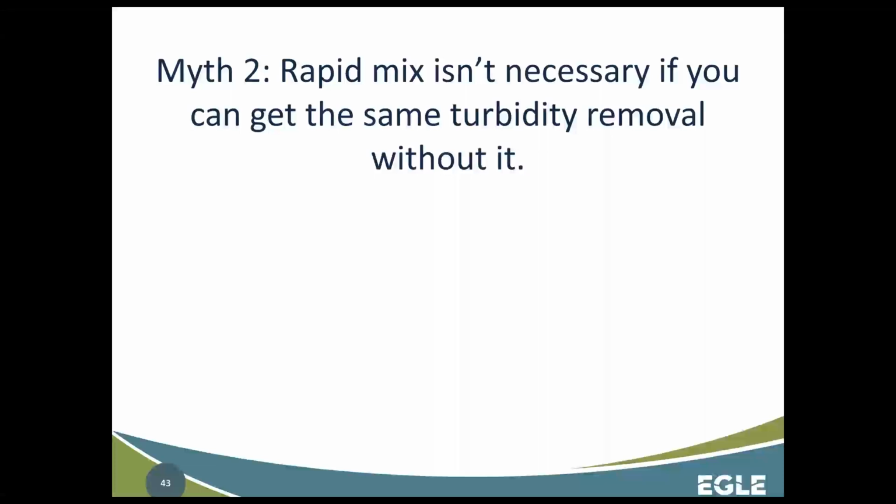So again, turbidity is a surrogate. It's a very useful surrogate, but at the end of the day, we need to make sure that we're doing proper coagulation so that we are removing as many of these pathogens as we can prior to the final disinfection barrier. And just like we touched on with the low turbidity source waters, just because you're hitting your turbidity goal doesn't mean that you've necessarily removed as many of the pathogens as possible.